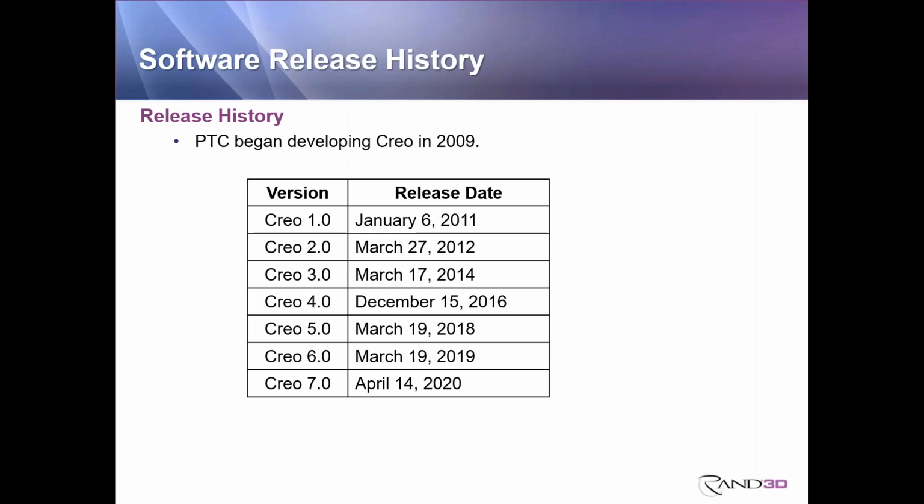Creo Parametric 3.0 and earlier uses the older versions of the standards, ASME Y14.5 and ISO 1101, among others. In Creo Parametric 3.0 and earlier, you can place datums on axes and non-real geometry surfaces, and you can reference them to the geometric tolerance frames.